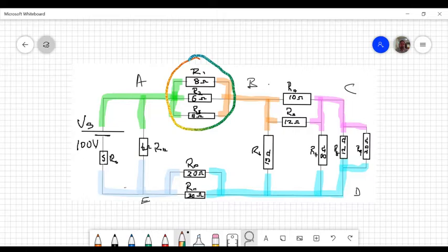But not only are they parallel, notice that the 8 ohm resistor is also connected to it. So is the 12 and the 10, but let's concentrate on the 8. Why just limit our concentration to the 8? Because look on the other side, they are also connected. Remember we said when leads are directly connected together, then they are parallel. So we can say that these 3 are in parallel also.